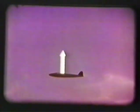The shock stall can also cause instability. For instance, changes in fore and aft trim. First, lift increases slightly just below the shock stall. This causes the aircraft to gain height, that is, assuming the pilot takes no correcting action. Next, at the shock stall, the sudden loss of lift puts it nose down. As the Mach number increases, the bottom shock appears and reaches the trailing edge before the top one. This forces the nose up a little.